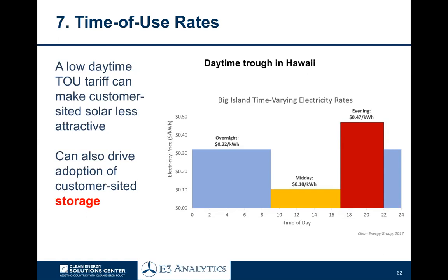That's one. Another thing that may start to get attractive is to actually install the solar panels facing westward, so that the production profile of the PV system shifts later to the day, so that they're producing more power between, say, 5 p.m. and 7 or 8 p.m., therefore able to tap into that higher time of use-based compensation. So all of these issues are connected, and they impact the fundamental economics of investing in solar.